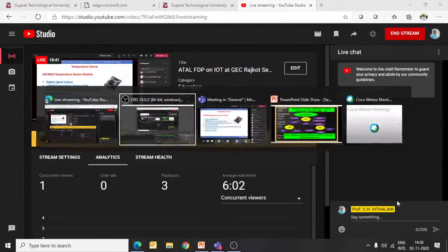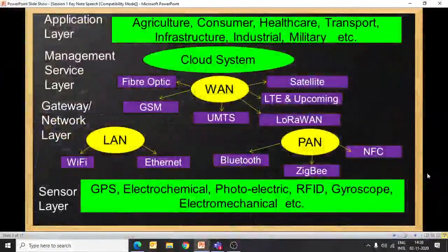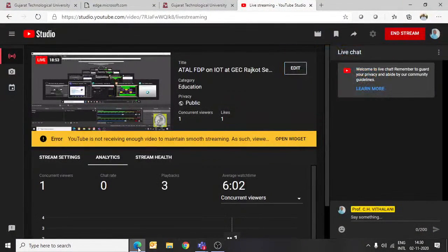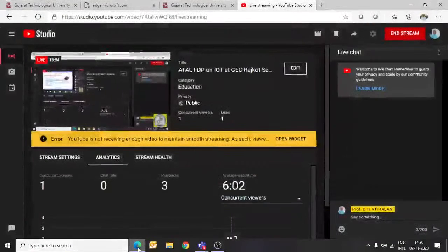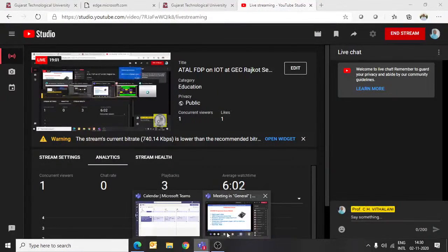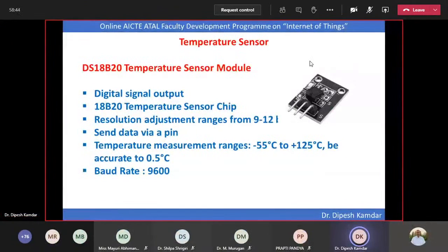I can just fetch the information from the sensor module, and find out what the temperature is there. So basically digital sensors do not require calibration. We just need to fetch the data and convert it by looking at the lookup reference table, converting the digital data to the measured quantity.